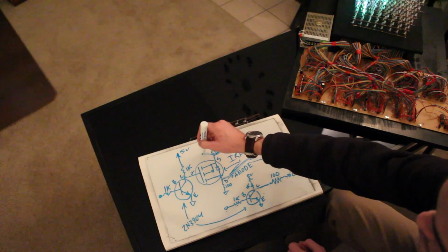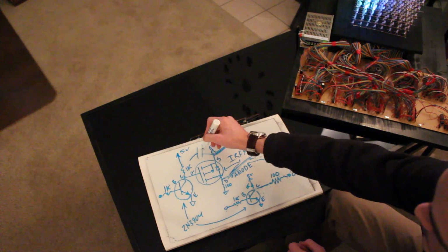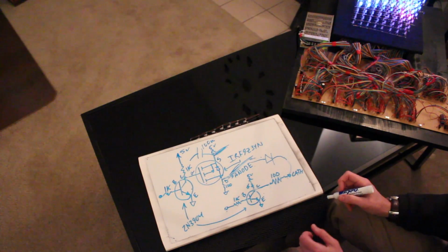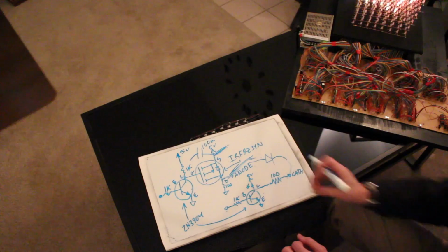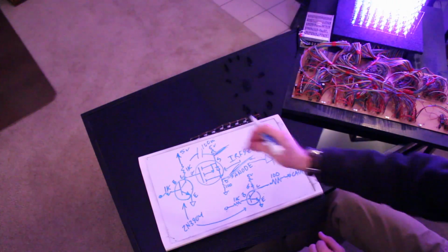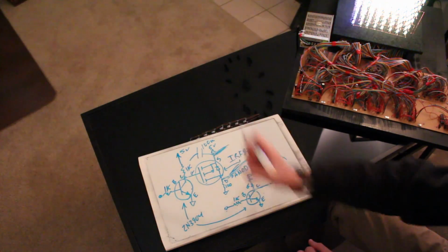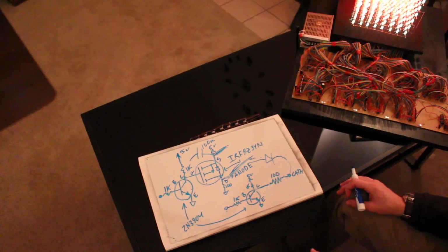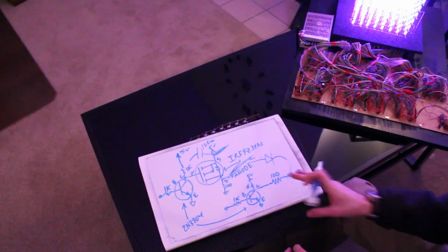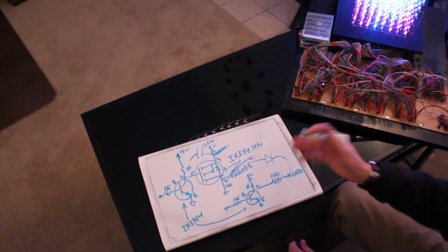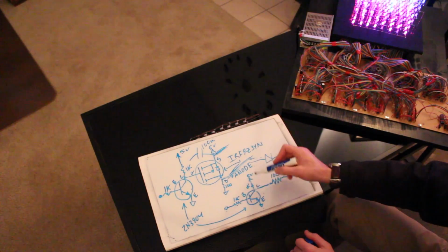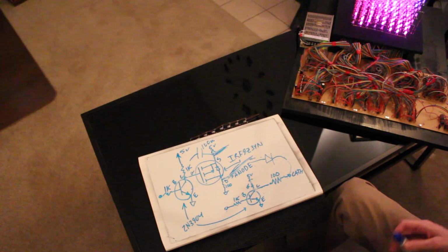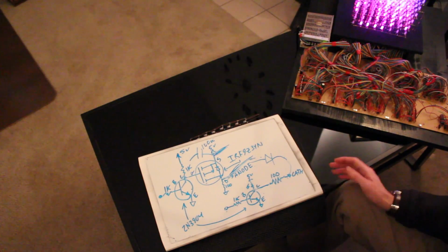So I put some giant caps in here, like I think a couple hundred microfarads, probably even a few thousand microfarads. So I put in some heavy duty caps right there, just so you have a nice stable supply and you're not really yanking it down too hard. And of course I put 0.01 microfarad capacitors everywhere on this circuit, when I say everywhere, just like on the digitals, on the supplies, not anywhere else on the signals that would throw things off. Okay, so now that's pretty much that circuit, and that's all really I have to talk about.